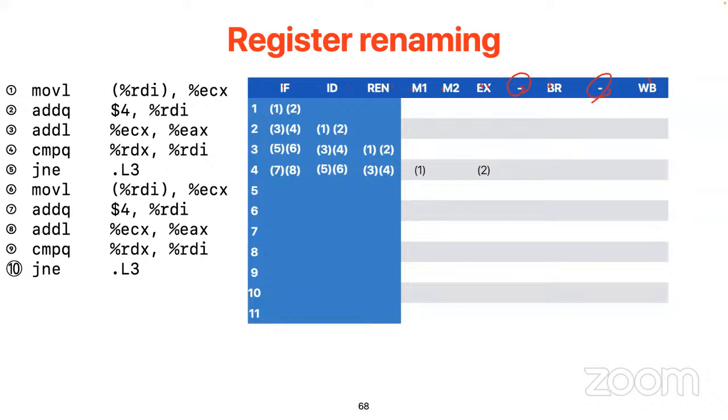It doesn't mean that the instruction needs execution. It just means that the instruction cannot be written back or committed, because right now we have to prevent those structural hazards. And if we have a 2-issue processor, it means that only 2 of the functional units, or the first stage of each functional unit pipeline, could have instructions.